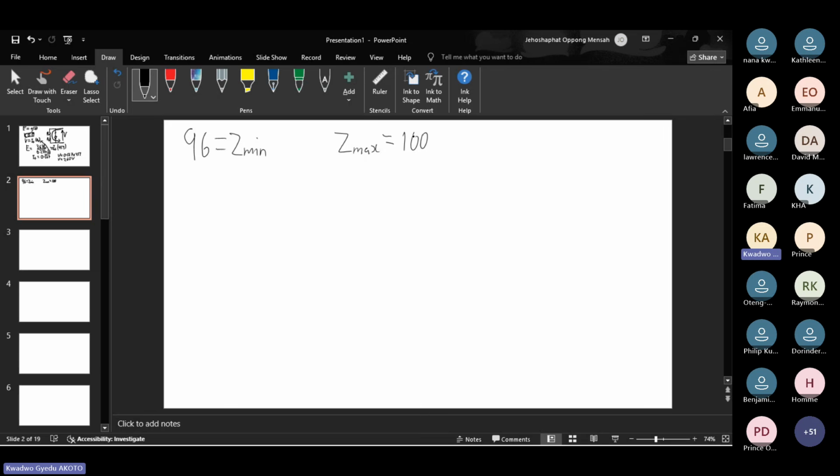Okay. So with this in mind, we also know that the number of slots must be greater than 12. So our number of slots, S min, but then S max must be less than 18. So S max is 17, and then S min is 13. Okay, so the maximum and minimum number of conductors per slot, fairly easy, this one.